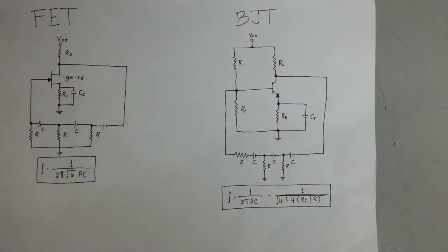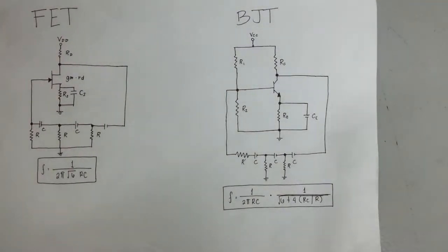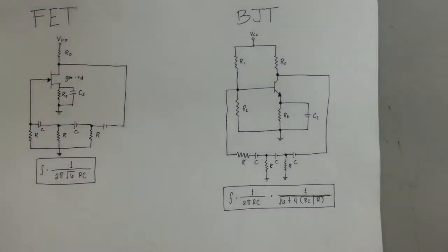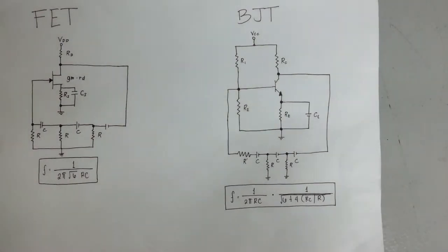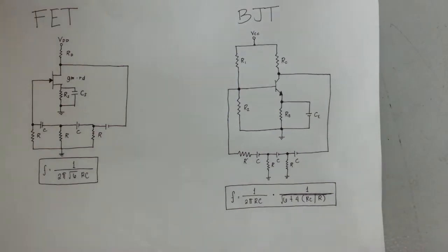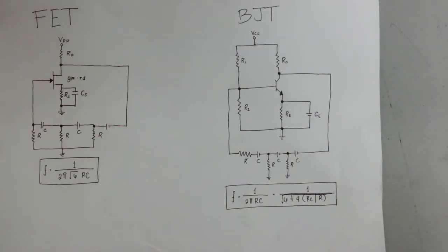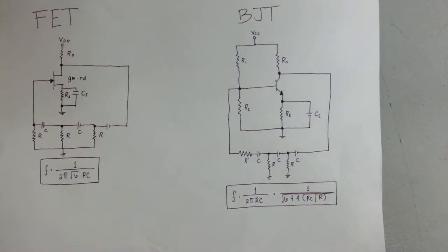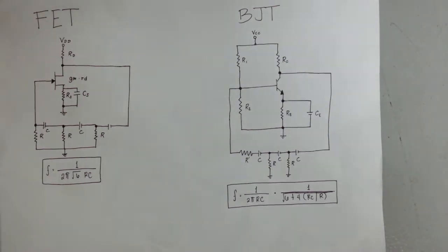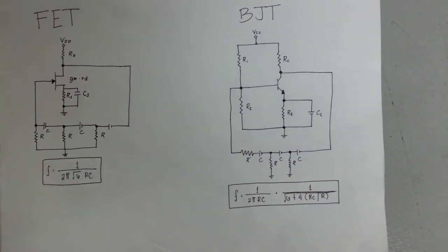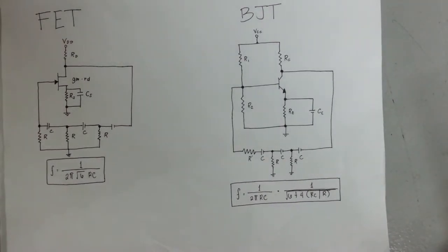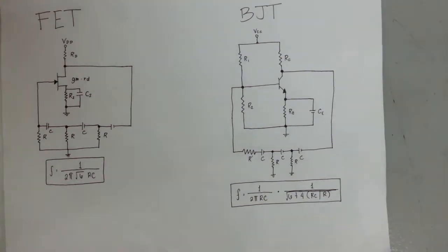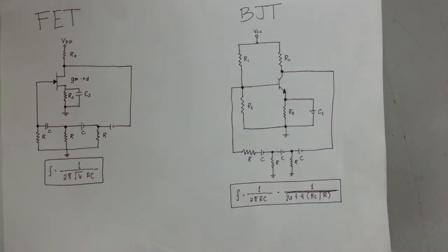The FET device parameters of interest are gm and rd. We should assume, as a very good approximation, that the input impedance of a FET amplifier stage is infinite. The output impedance of an amplifier stage, given by RL, should also be small compared to the impedance seen looking into the feedback network, so that no attenuation due to loading occurs. In practice, these considerations are not always negligible, and the amplifier stage gain is then selected somewhat larger than the needed factor of 29 to assure oscillator action.